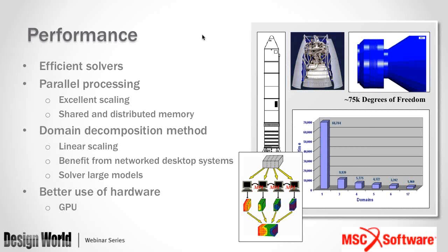So this can deliver much better scaling. What happens with this approach is every single task of the FEA solution is parallelized. By that I mean reading input files, stiffness matrix assembly, matrix solution, and output generation. All these tasks are run in parallel, which means you achieve more efficiency in your solution process.